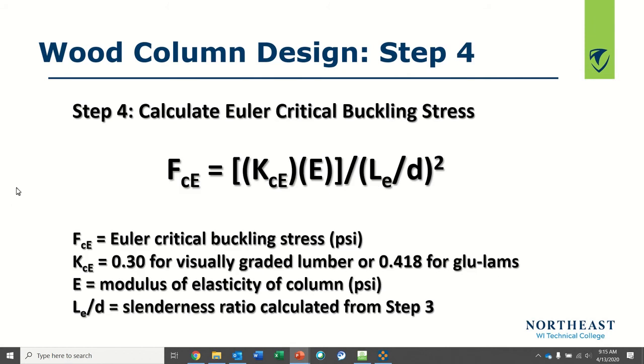Step four, calculate Euler buckling stress. I'm going to write the formula down: FCE equals KCE times modulus of elasticity divided by my slenderness ratio squared.